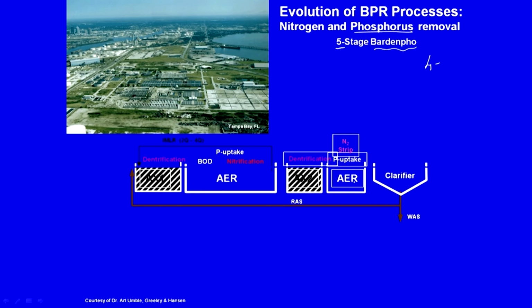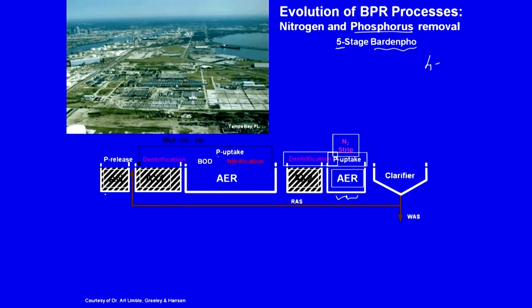And so, in the aeration system, phosphorus uptake will take place because we are again pumping air, and some more phosphorus uptake will take place in this aeration. And by adding this anaerobic tank here, for the system to experience stress and see to it that phosphorus accumulating organisms thrive well, what do you need? You need alternating conditions of anaerobic and aerobic. So, obviously we have aerobic, but now we need the anaerobic tank also. That is why it is called the 5-stage Bardenpho process.